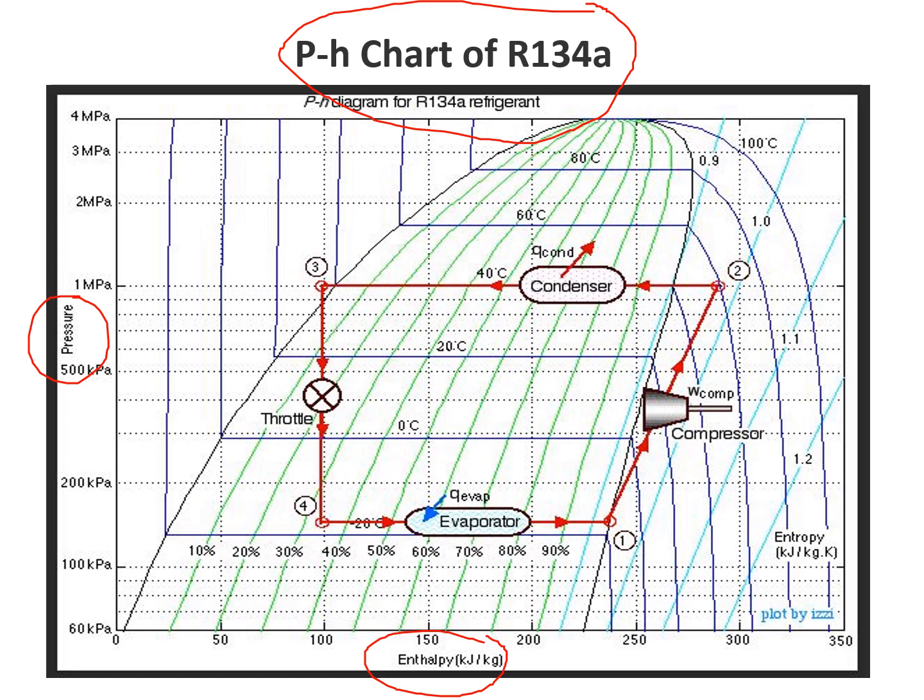Now you see this is the state 1, that is the entry to the compressor, this is the exit of the compressor, the discharge side, this is the exit of the condenser, and this is after the expansion valve. These are the different states. Okay, so in this we draw the pH diagram on the pH chart of R134A. How do we draw that? You see these blue lines, these are the temperature lines. You see 20 degrees Celsius. So this is the 20 degrees Celsius constant temperature line.